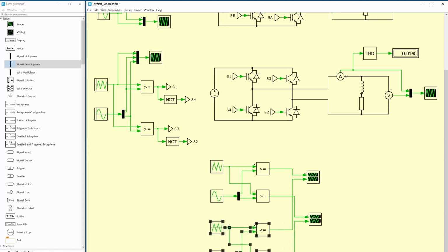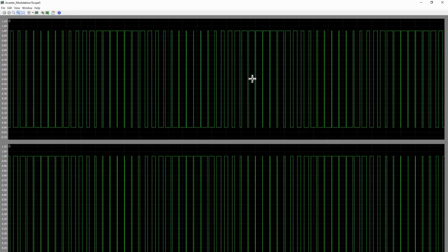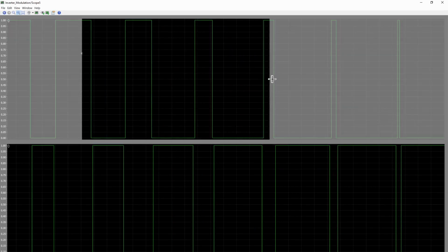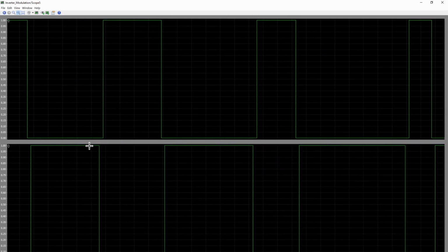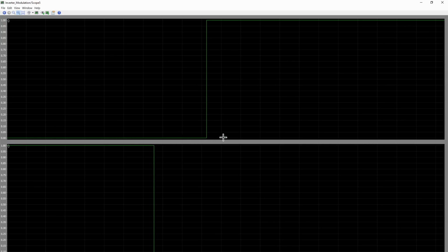Okay, now this is a unipolar design. Okay, let's see the simulation here. Look at this waveform. Now let's examine the dead band. If you look from far away, you'll not notice anything, but if you zoom in, look at this one. Now this becomes 0 first, and after this becomes completely 0, this will jump to 1, right? Look at this one here. This is the dead band, from this time to this time.